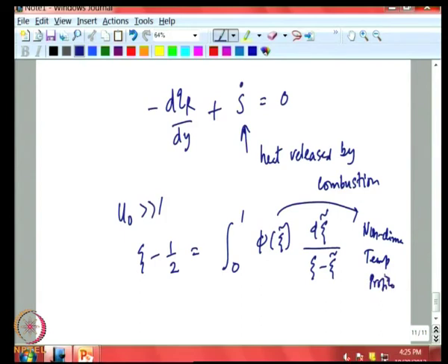So, this is a very interesting expression for the large path length limit, wherein you do not see any line structure parameter in your expression. You are merely seeing the role of the logarithmic limit, because in this limit we know that the band absorptance goes as A0 log u.